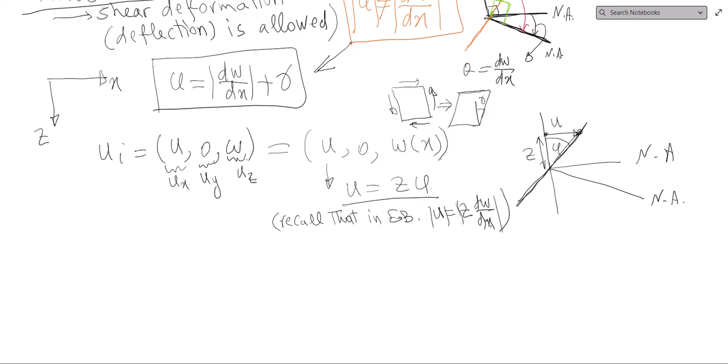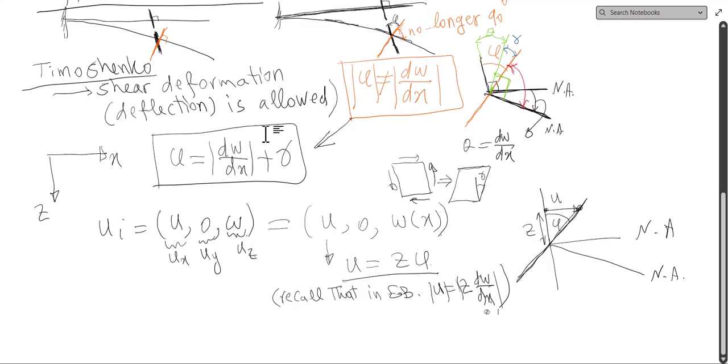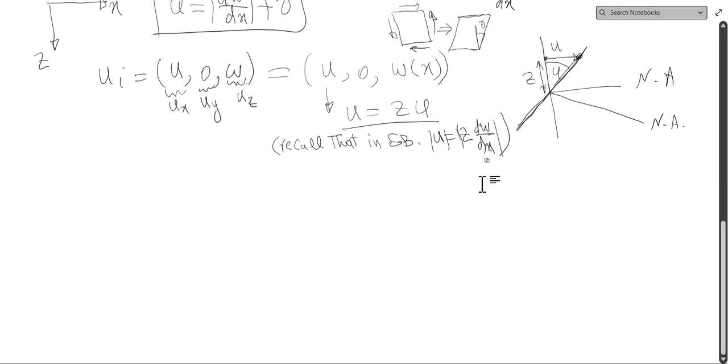Now it is not dw/dx. Phi is no more dw/dx. Phi has another value which includes the shear deformation, or shear strain if you like.